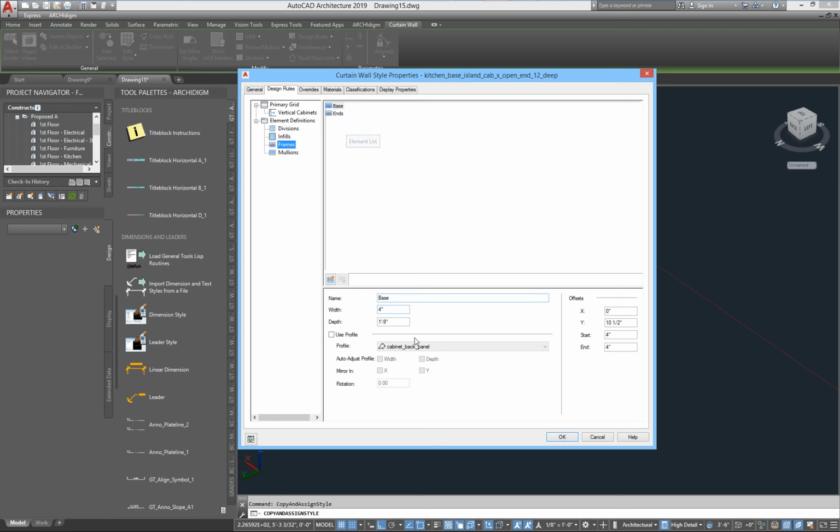So it has a base that I want to shrink by 12 inches. So I'm going to pull 12 inches out of everything. I'm going to pull 12 inches out of the base. And this is the offset of the base. So I'm going to reduce that to half of the 9, so 4.5. And then the ends are going to be easier if you just do half.